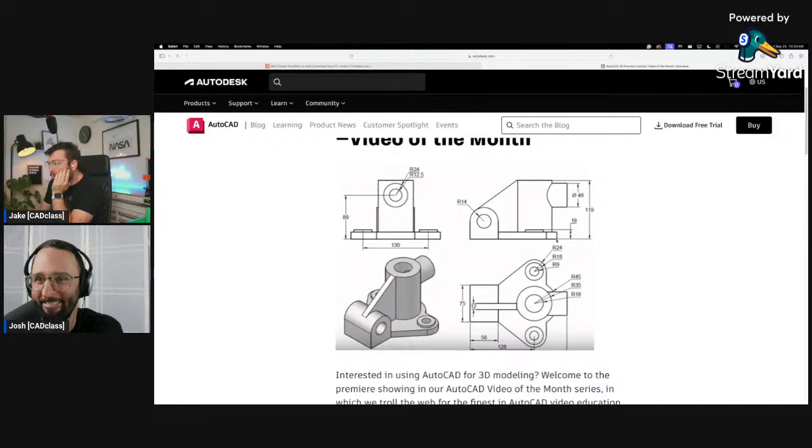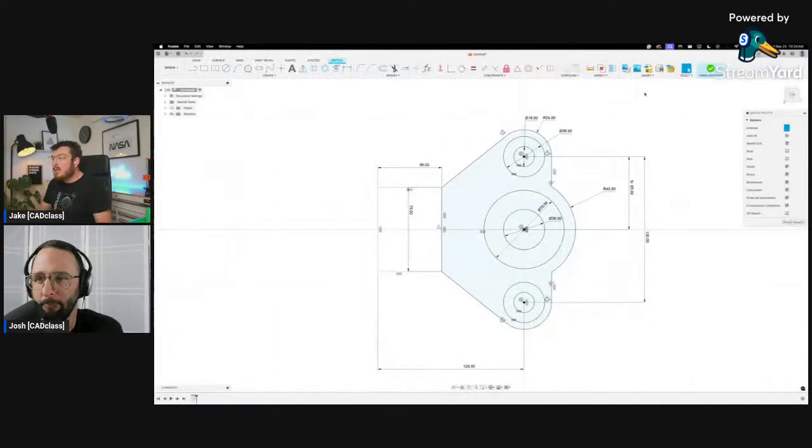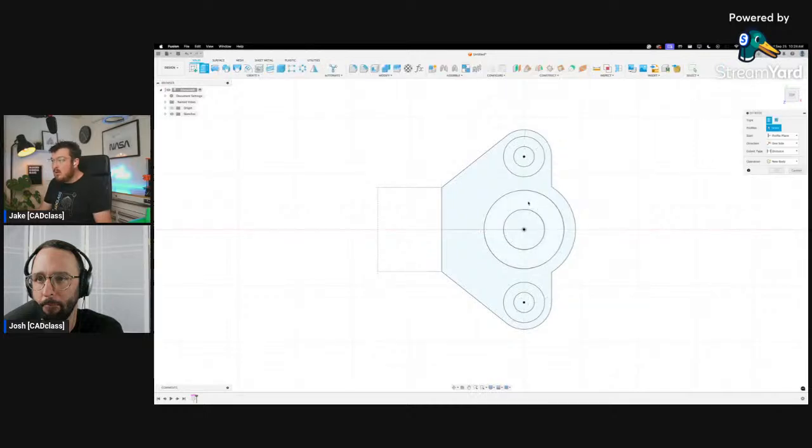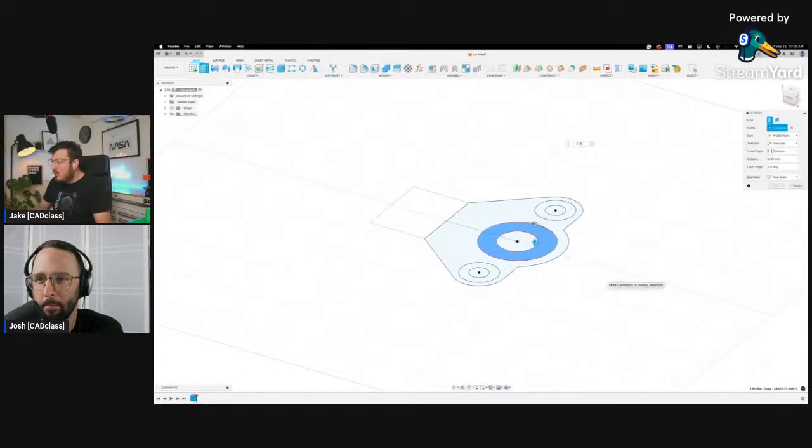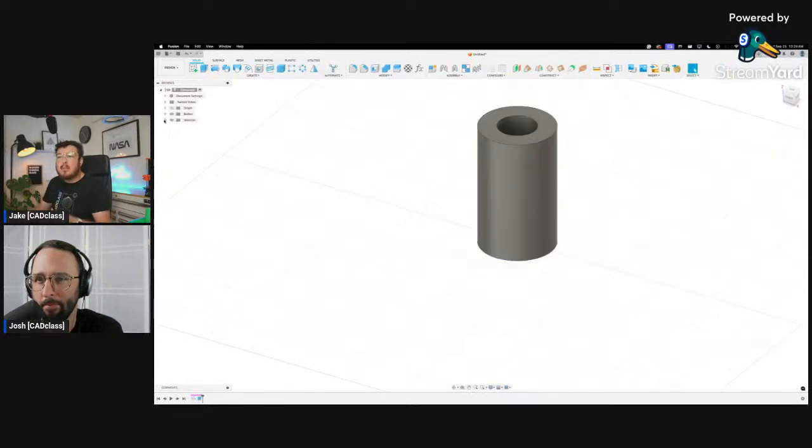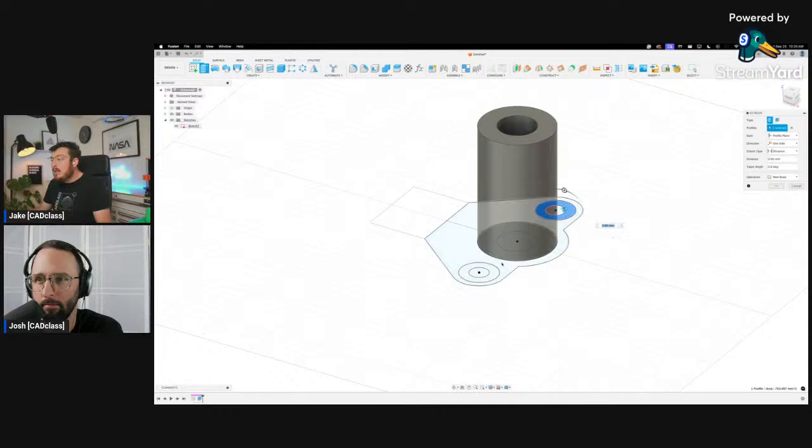Okay. Well, let's say we can extrude that section to the whole height. So I'm going to make that 119 tall, so I can at least start on that. So this circular section, 119 millimeters tall. I'm going to go back and turn the sketch back on. Those little tiny indents, those are going to be 19 mil tall.